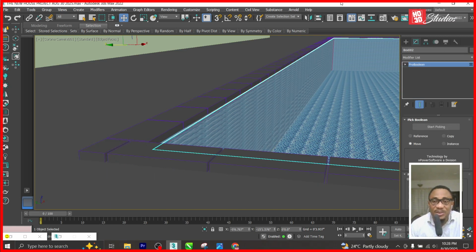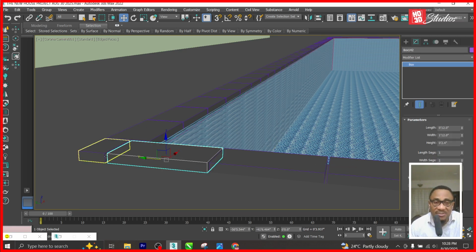You chamfer the edges before you start duplicating them, before you start arranging them. The very first one you create, you chamfer the edges, you create gradients, curves around the edges. That would naturally make them less sharp. If you see your sanitary ware, your toilet bowl, or your sink in the bathrooms, they don't have sharp edges. It's an intentional thing. All right.